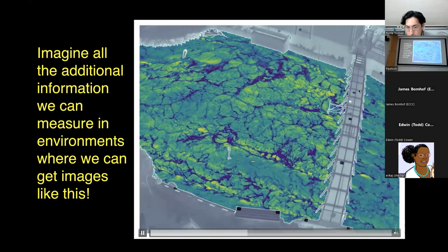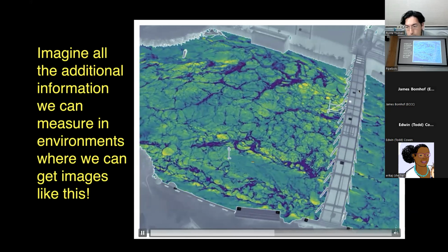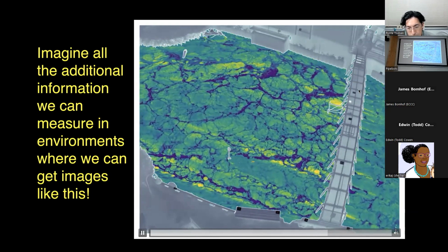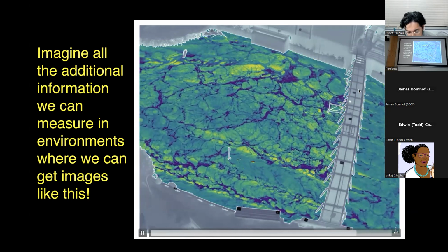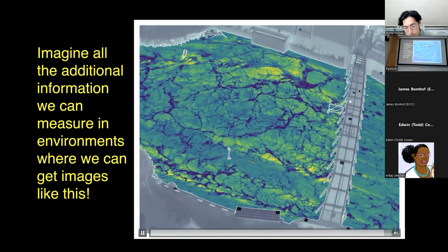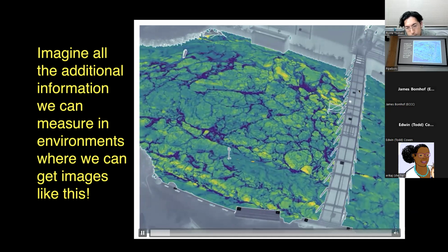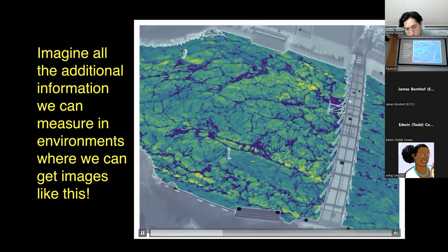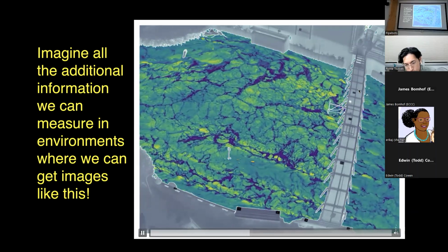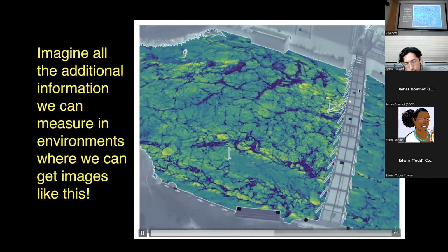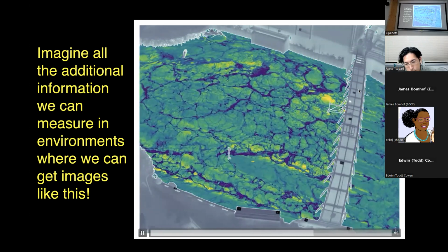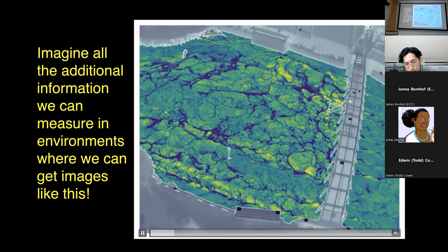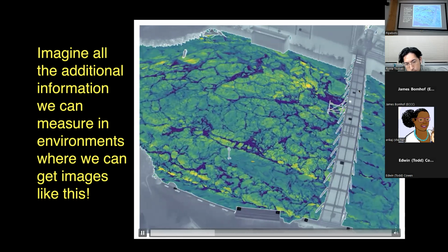We do have a little bit of experience, and that's probably something that will be growing significantly in the coming year. But in the work I presented last year in California, we did back out the bathymetry from Sutter Slough from the turbulence field, using the technique that Erica developed, and it worked really well. The key is that you need a technique that's resolving at least the larger scale eddies. You can see them here, and it's pretty clear that in an unstratified flow they are representative of the flow depth.